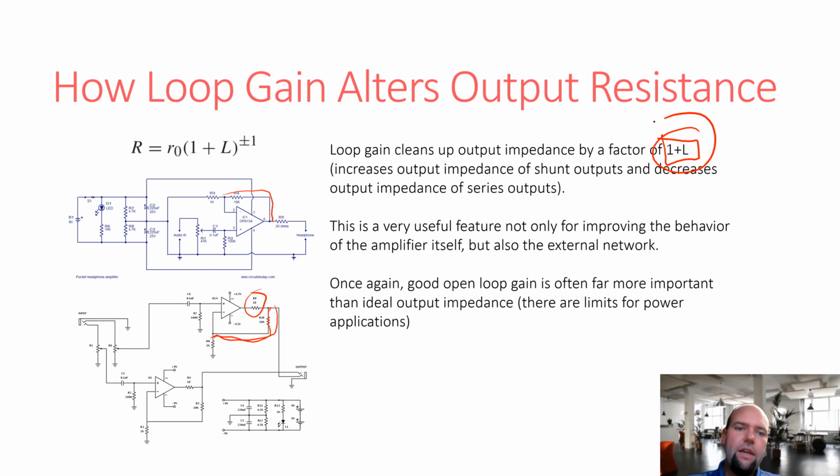So this circuit is not going to behave like a 10 ohm output resistor. It's going to behave like a 0.01 ohm resistor. And that means that the output voltage will still be the same or pretty much the same, even though we added that 10 ohm resistor. So people might say, well, come on, if it maintains the same output voltage, how is that actually protecting the amplifier? Because you have to think about what it has to do to maintain the same output voltage. In this case, as current starts to flow, this op amp is going to produce a much larger voltage across this resistor in order to produce the correct voltage at the output.